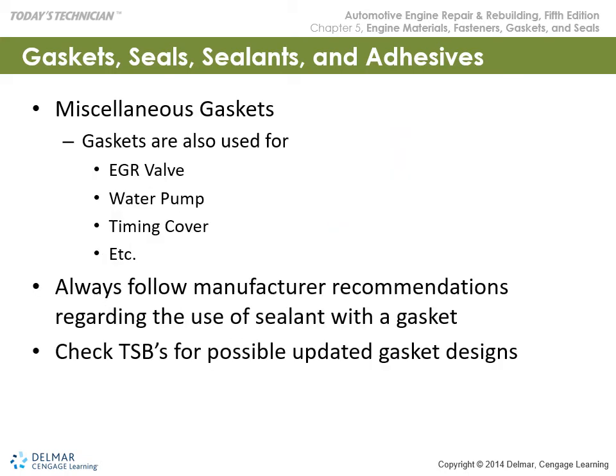Okay, miscellaneous gaskets: EGR valve, water pump, timing cover. Follow manufacturer's recommendations, and check technical service bulletins. Technical service bulletins can give up a lot of information. When the manufacturer has a failure that occurred over a certain percentage of time, the technical service bulletin can nail the problem for you and bring you to a repair situation faster if it's a common failure. So you always want to check your TSBs and see if there's a common failure that's related to what you're working on.